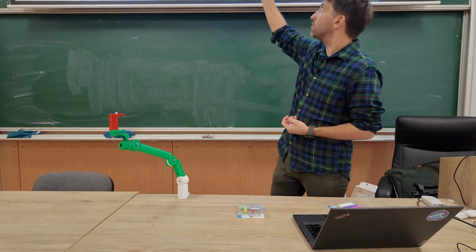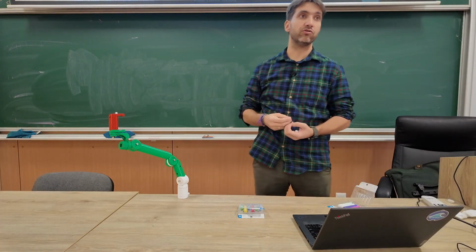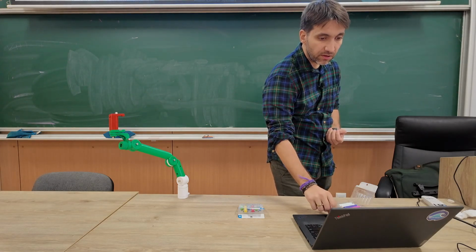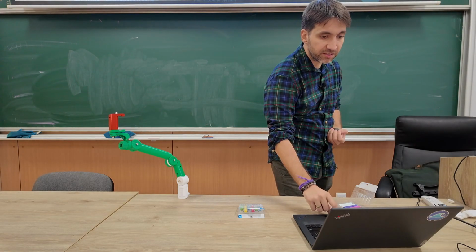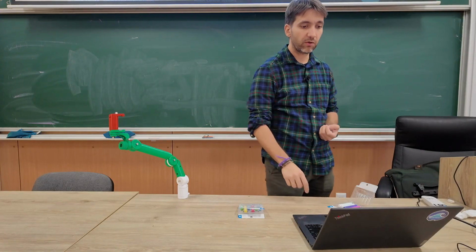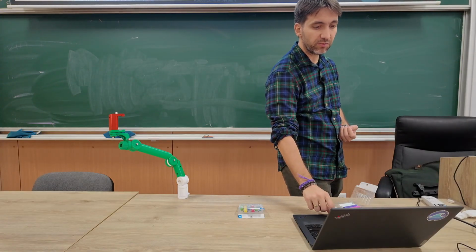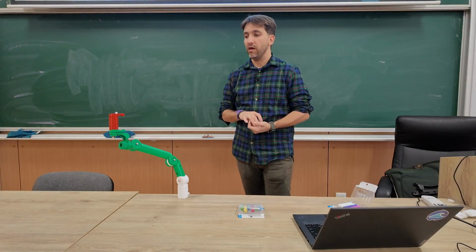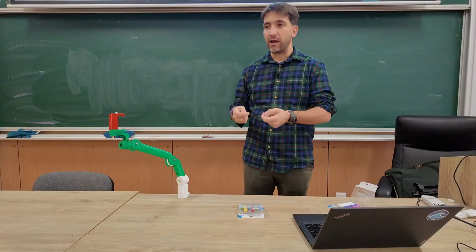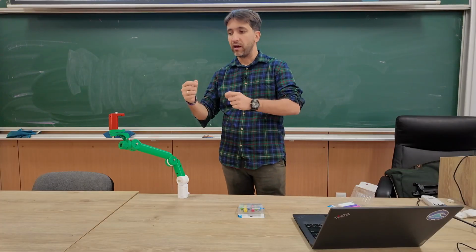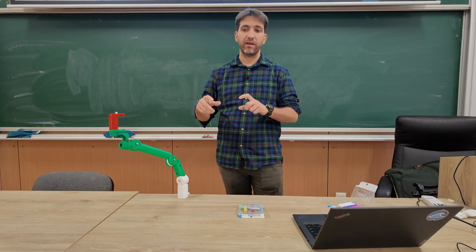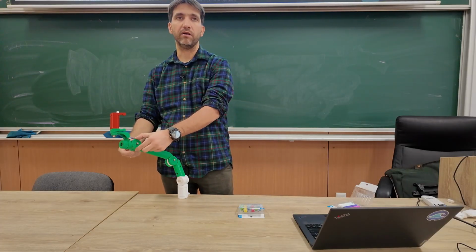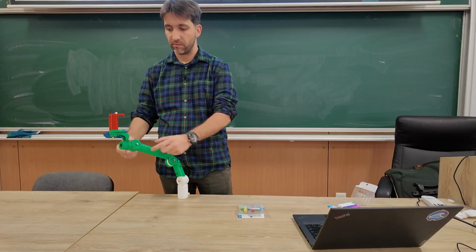So in this block diagram here, the action should actually be torque, because if this is my process that comes here, that's the input. That's how I can affect the response, which would be joint coordinate, joint velocity, joint acceleration, right? So yes, indeed, at low level, I am going to control voltage and current that goes to the joints, but I have to modulate that so that I end up having a certain torque here, right?